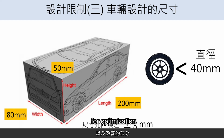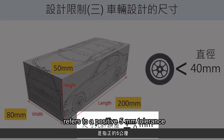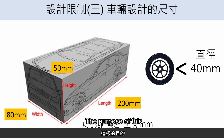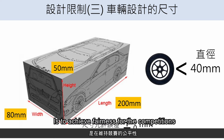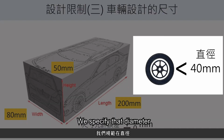for optimization and improvements. The allowed tolerance is within 5 millimeters. Here the 5 millimeters refers to a 5 millimeter tolerance. So basically, we can exceed 200 millimeters car length, 50 millimeters car height, and 80 millimeters car width, but it cannot be smaller than the original dimensions. The purpose of this is to achieve fairness for the competitions. Also, regarding the dimension of the car wheels, we specify that the diameter should be less than 40 millimeters, that is, measuring less than 4 centimeters in diameter.